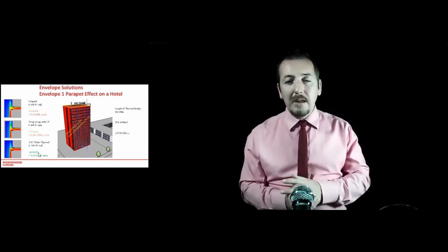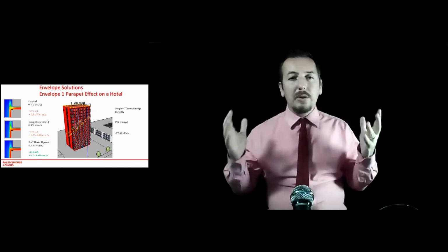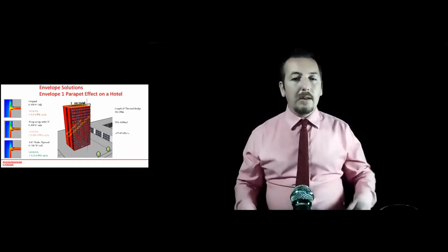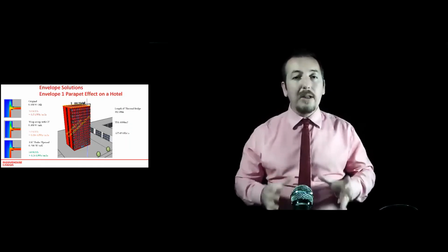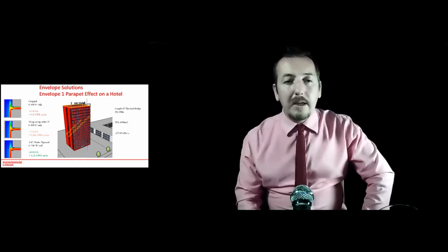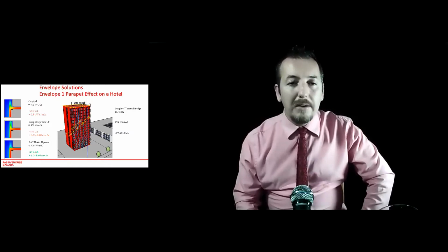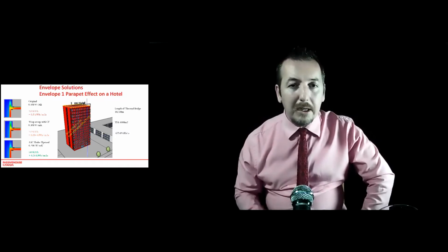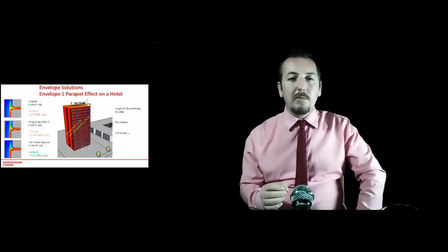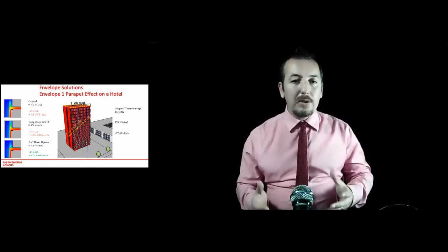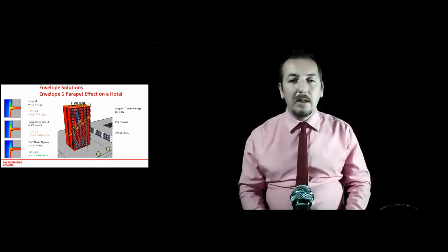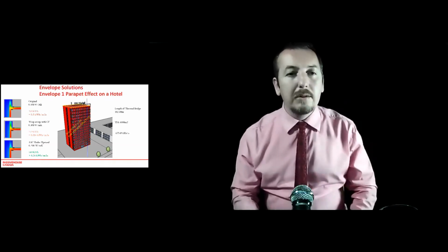So you can see that if you have a huge hotel or a very large residential building or just a very large building, you can absorb thermal bridges that bit easier. But as you'll see in a minute, what you have to watch for is the magnitude of the thermal bridge. Okay, in an example in a minute, I'm going to show something where it's a similar detail, but it actually blows it out of the park.